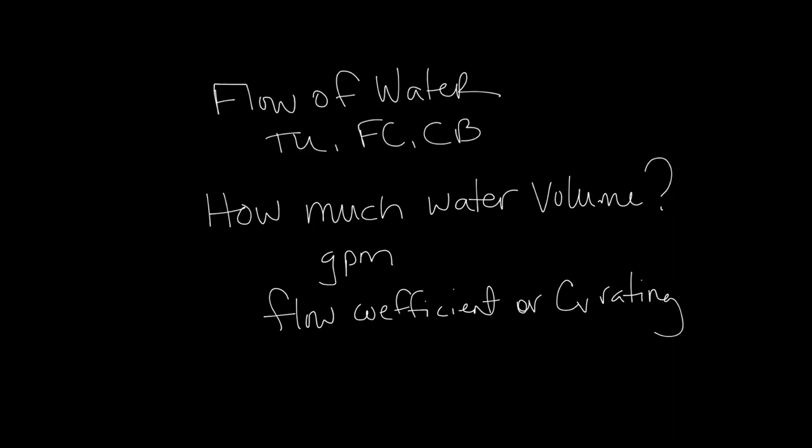We can relate CV to GPM and pressure drop using the following equation. CV equals GPM divided by the square root of the pressure drop.